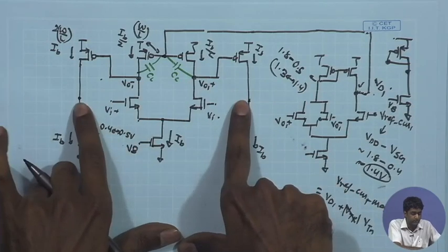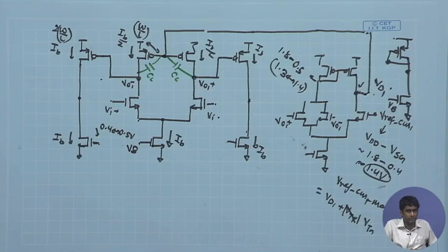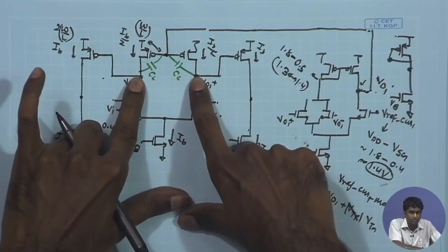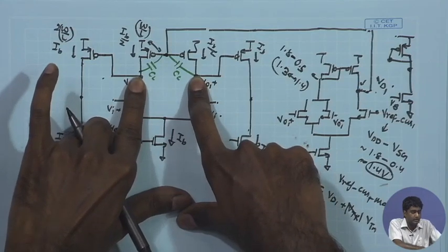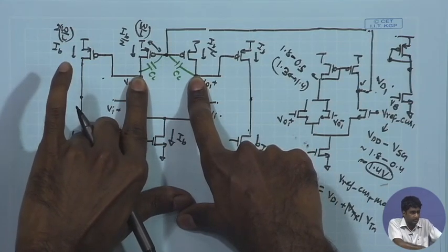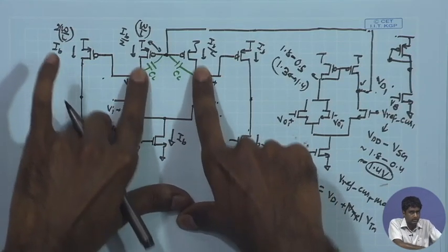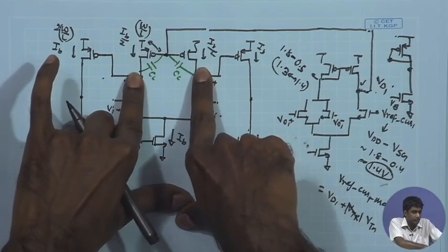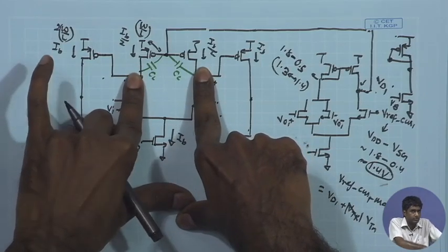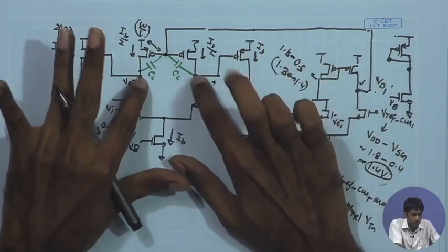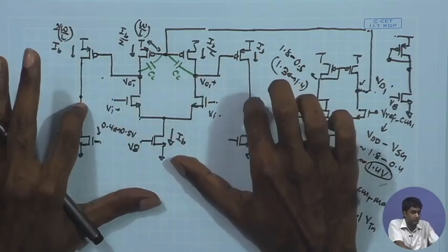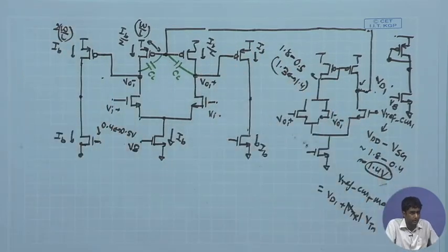As compared to this, the swing here is much larger, especially if you are talking about the first stage, few tens of microvolt of signal. Here you may get few millivolts of signal, and therefore it is not going to be so critical with respect to swing. So, even 100 millivolt of swing available over here is good enough, 50 millivolt is good enough, much more than required. So, I do not worry so much about swing here, but yes, swing will be more of a concern here, especially if you are having a second stage of front end amplifier with programmable gain.